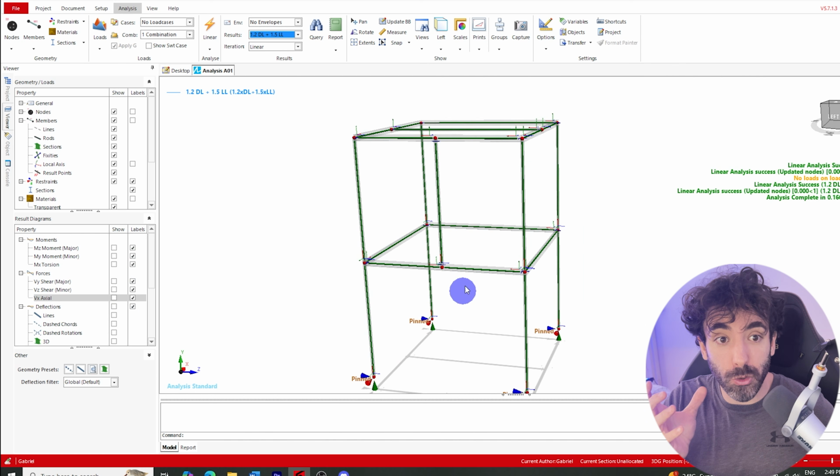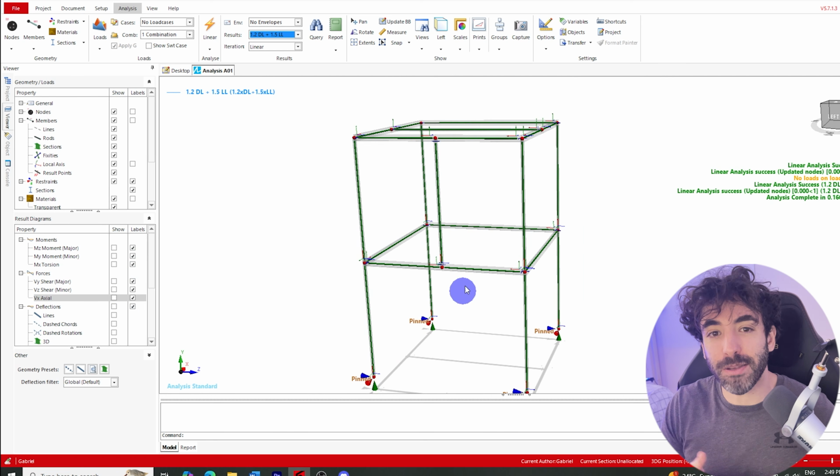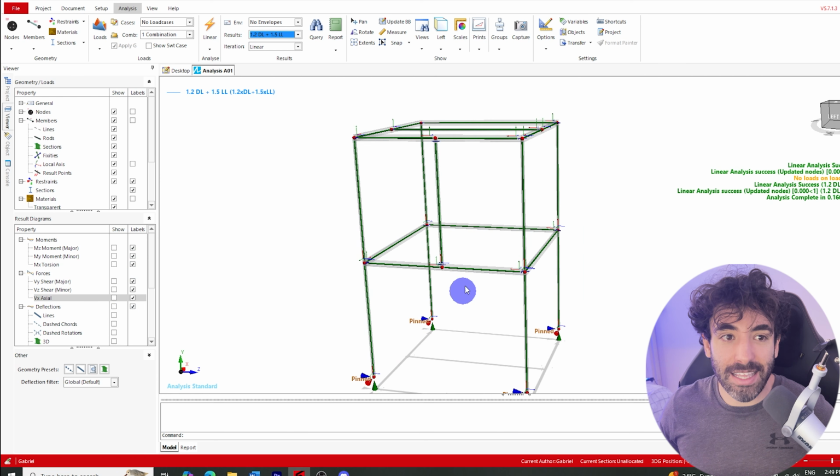That's what you would understand by reading these diagrams, but at the same time you have to make sure that the builder will be able to prop the floor framing while the column is not in place. You have to make sure that the beam can withstand construction loads without the column in place. Those are little details that I like showing students so that they can understand the load paths, they can understand reading diagrams, they can understand making sure that the construction process will be suitable for how you design the structure to behave. Play around with it.